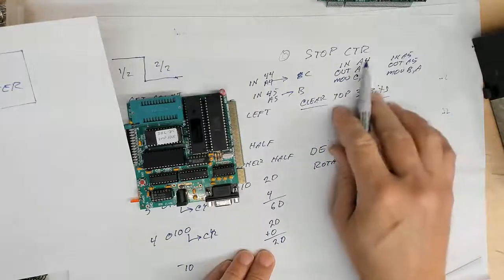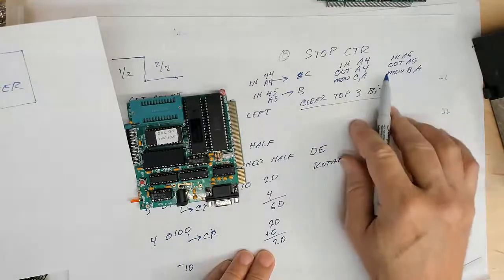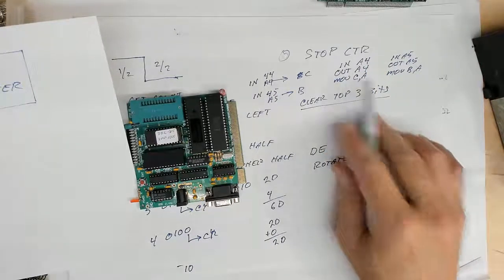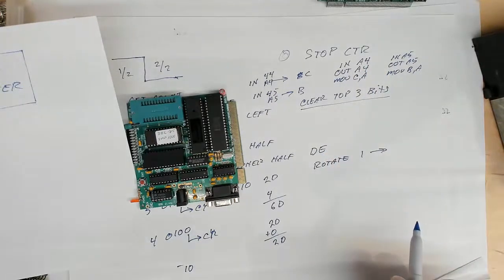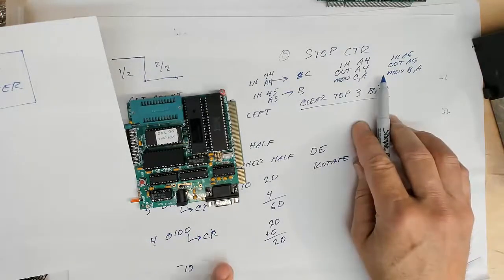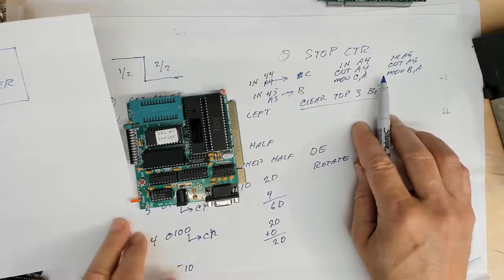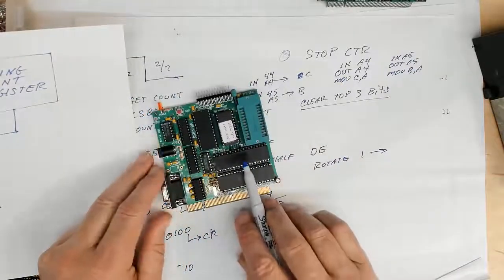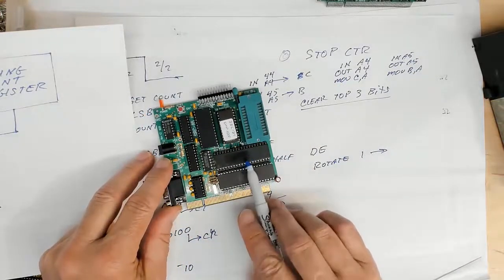If we wanted to start counting again where it left off, we would need to take those values that we received and reload them back into those registers. Okay, so that's the final little caveat to using this timer. I think that's everything at this point. You should be able to program this timer, and anytime you want, go back and read that value.